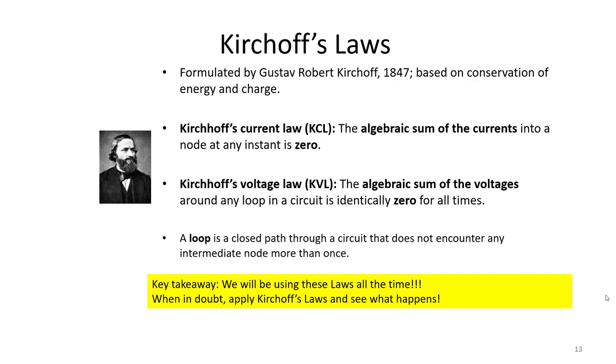Kirchhoff's current law, which we often call KCL, tells us that the algebraic sum of currents into a node at any instant is 0. So what that means is current is conserved.